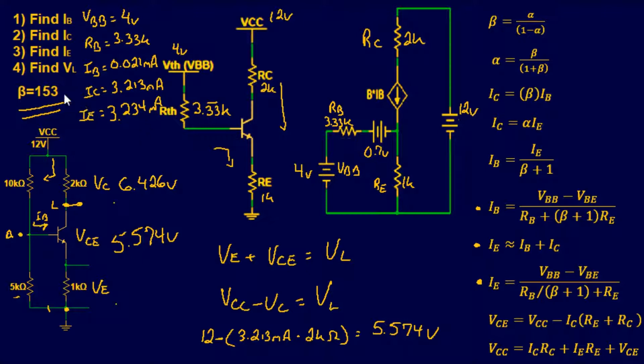It's very rare when I ask for that in that way, but I want to go over it that way so you're aware of how I came up with these. So remember, there's always voltage drop right there, your collector resistance and your emitter resistance. On our next lesson, we'll most likely go over our small signal model and our AC analysis of BJTs, and we're going to talk a little bit more of the DC analysis going into the AC analysis. Hopefully I gave you enough information here to confuse you and make you dangerous, and I hope you all have a good evening.